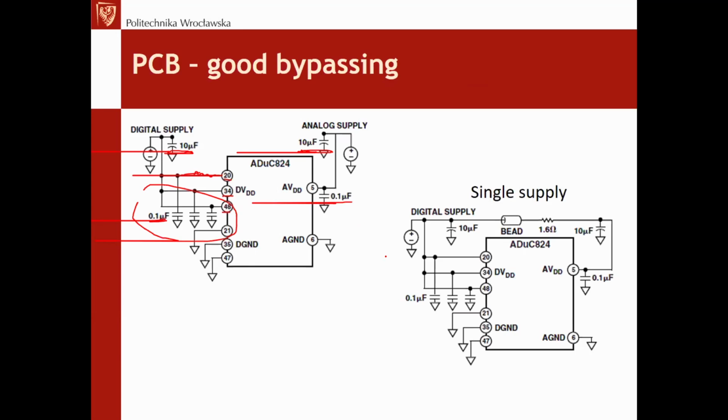From practice, the first shot is 100 nanofarads. That's the first shot for the decoupling capacitors, but it's not unlikely that as you get more skilled, you will see that sometimes 100 nano is not sufficient. Sometimes you have to add, for example, 1 nano, and additionally something like 10 picofarad. But that's not obligatory. The obligatory value is always 100 nano. So without thinking, each power supply pin is to be decoupled with 100 nanofarad.